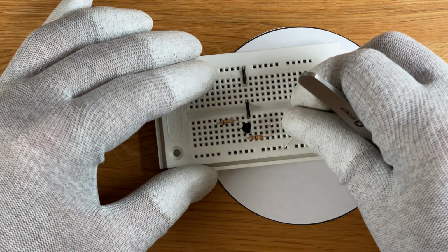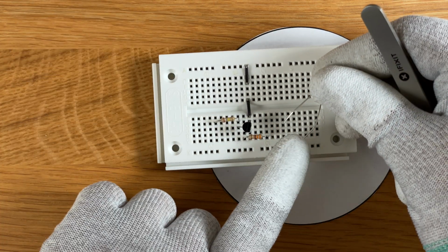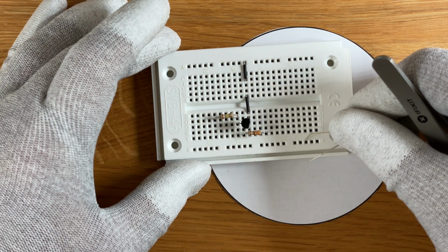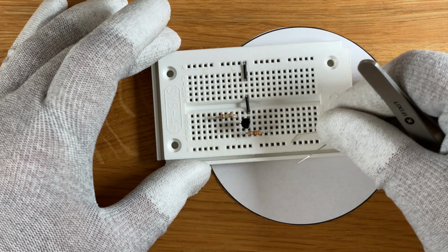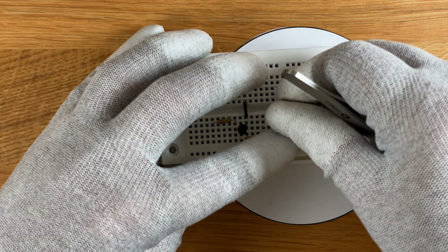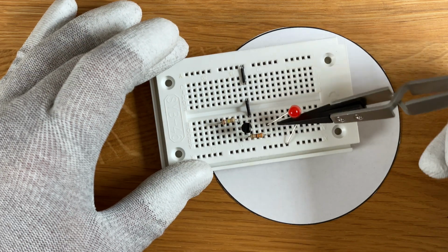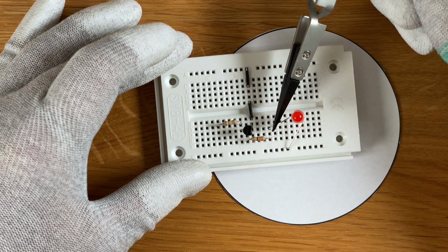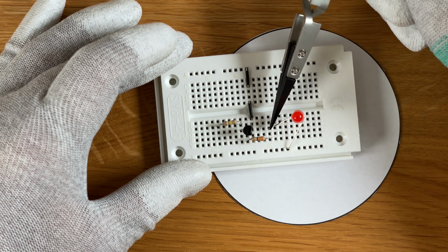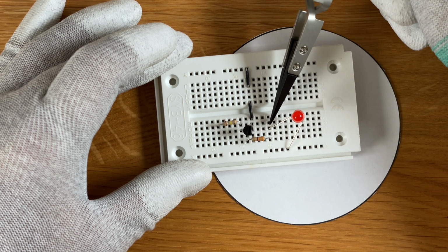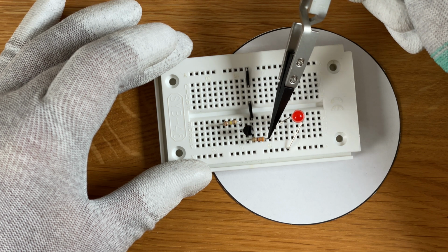If we pull it out, this side here is the positive lead. This has to be connected to the positive terminal of the battery, which is going to be connected to this power rail here. And the other side, this is the cathode. This is connected to the resistor. And we have made a video on how to use a breadboard before. And by pushing the connector, the cathode of the LED, into this column here, we ensure that it's connected to this side of the resistor.